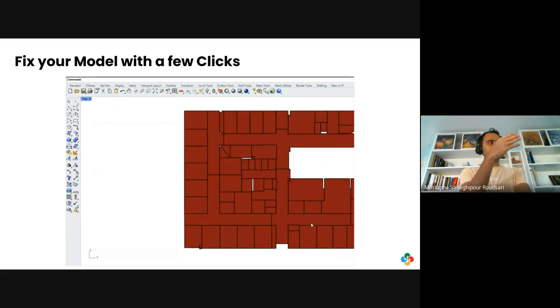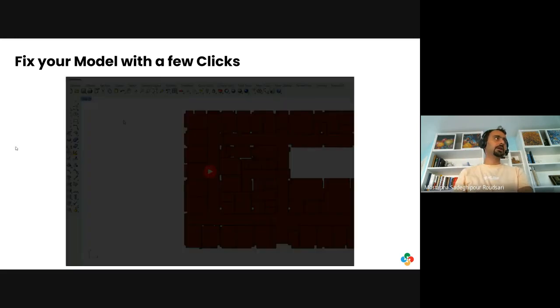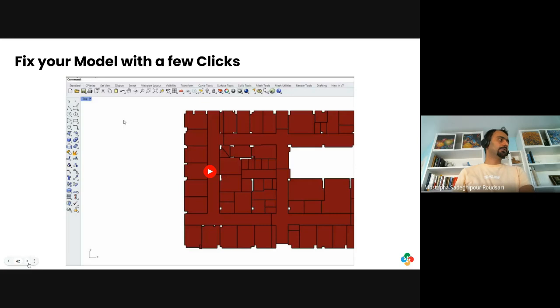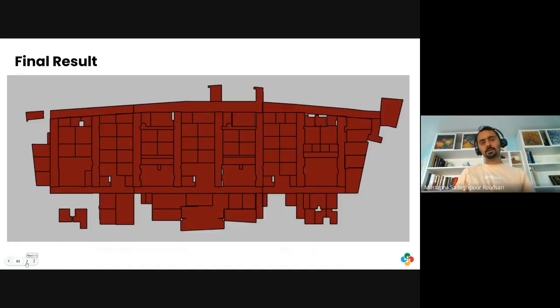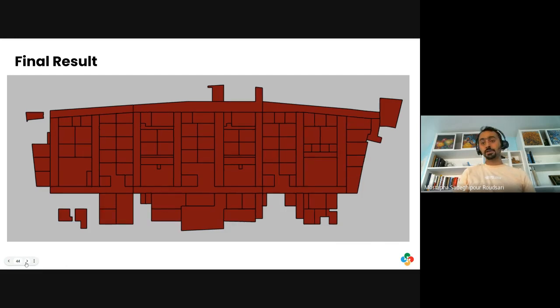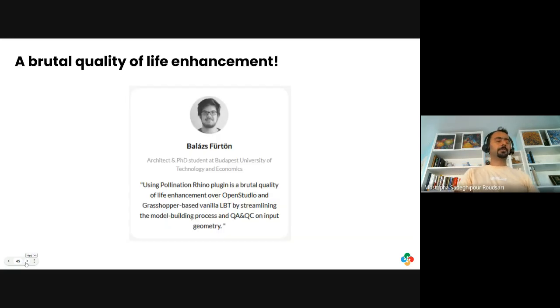It's feet because the model is in feet. If it's modeled in meters, it's really meters, and then it will clean it up for you. So Rhino not only has all these commands to create, but it has all the commands to fix. You can get from here to here in 15 minutes. And this is with the PO remove short segments.